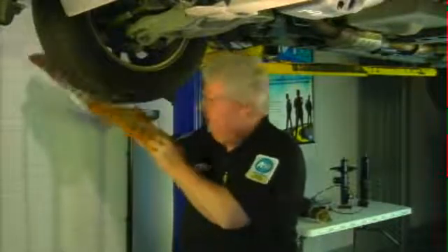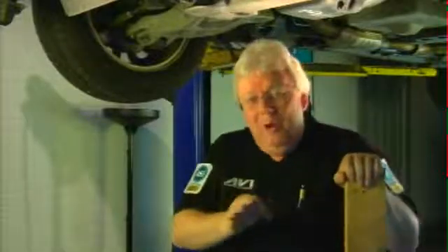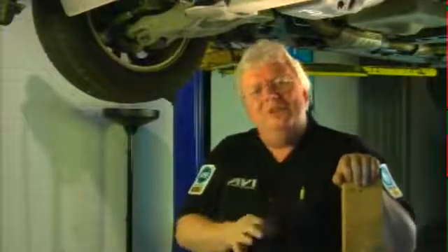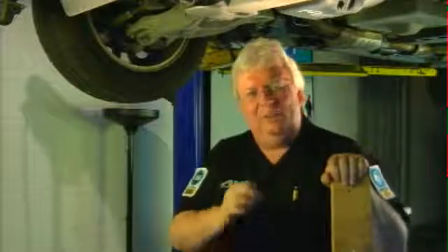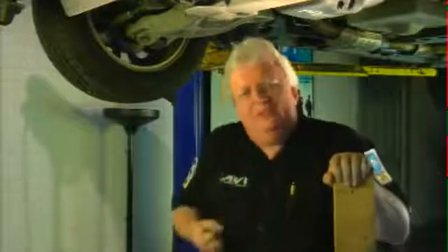with this big lever, the 2x4. And there's supposed to only be 0.06 inches of play. But guess what? That's almost nothing. So if you feel a bunch of slop, it is typically a load-bearing ball joint.